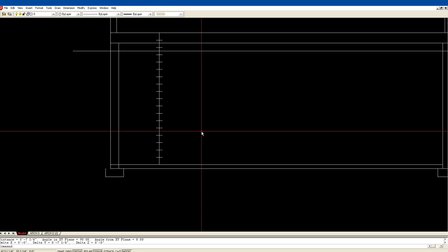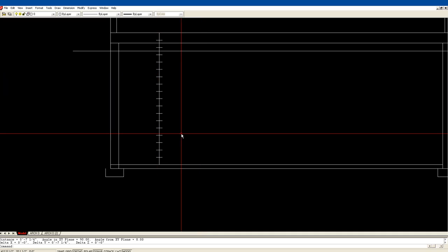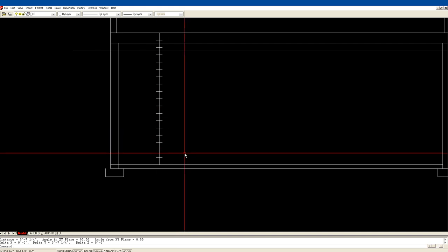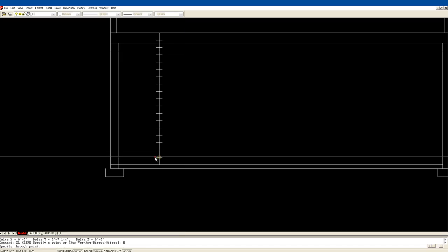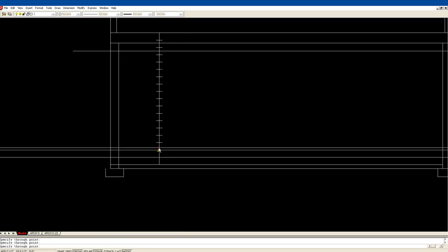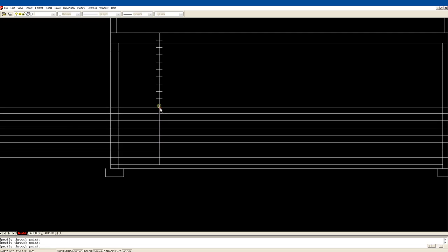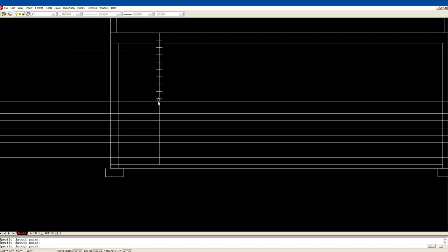Well, AutoCAD is saying that the way we're set up, it's 7 1/4 inches is what you're going to divide these by. So you got 18 times. So we're just going to draw X lines, and this time we're going to draw horizontal, and we're just going to pick on these nodes. Oops.